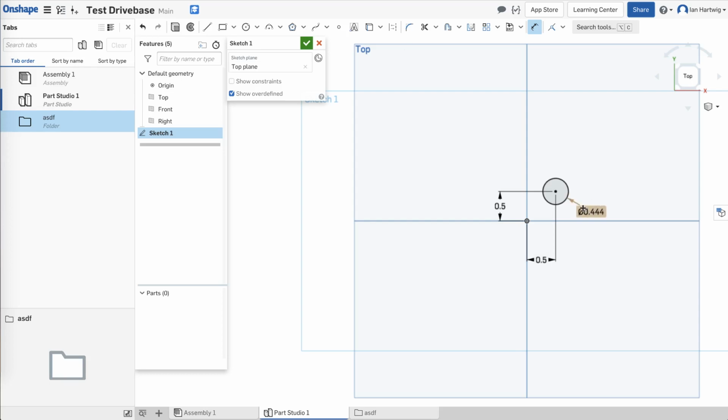Okay, hopping back over here. To edit a dimension that is already in the drawing, we can just double click on this and put in what we found from McMaster-Carr, 0.192 inches. Great.